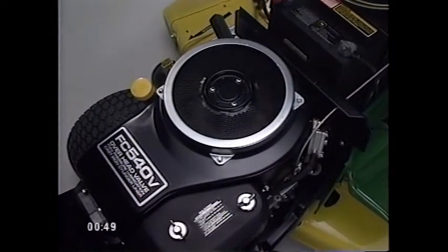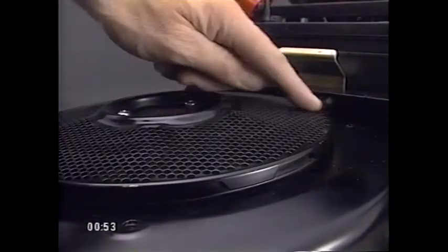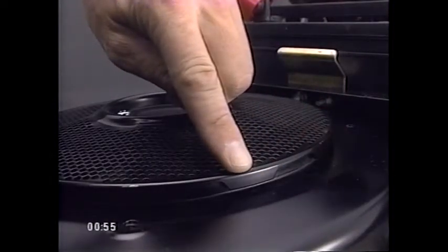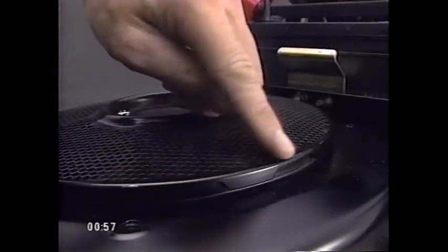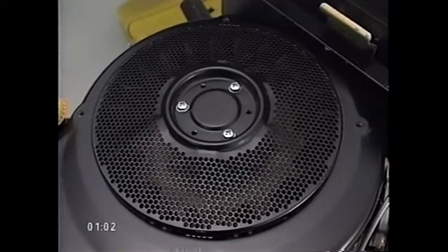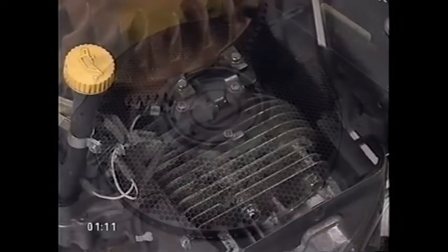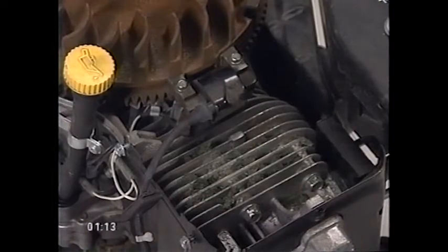Air is drawn into the blower housing through this rotating screen. Contour blades built into it chop up any grass or debris that enter and discharge it around the edges. Keeping the screen open is very important, since it provides the airflow for both the cooling of the engine and for the supply needed by the carburetor. Operating an engine in extremely dusty conditions may require that the engine shroud be removed periodically for cleaning of the engine fins and air passages.